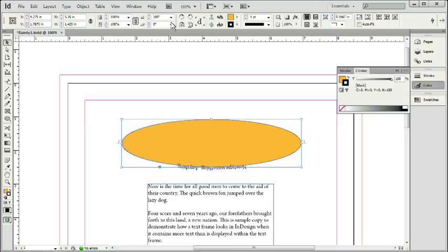Double-click in that Rotate Selection edit box in your control panel and change the 180 degrees back to 0, and hit the Tab key. This will flip the text back right side up. If that text isn't perfectly aligned, just adjust the entry and exit handles until it is.